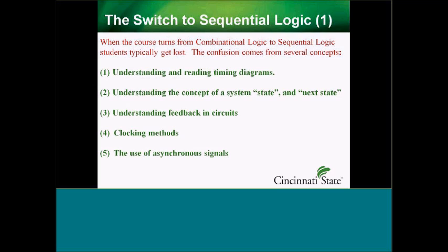If you're an engineering tech and you're going to be looking at logic circuits, you're going to put a bunch of connectors down. You're going to be looking at waveforms going through, and it's exactly what you're going to be looking at. There's going to be a system clock. There's going to be a bunch of signals, and you're going to try to make some sense out of it and see if there's anything that doesn't line up. So that's critically important. You can also do that in Multisim as well. You can put down a logic analyzer and look at the signals.